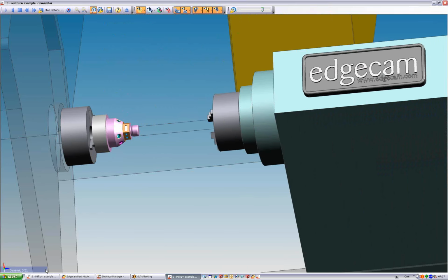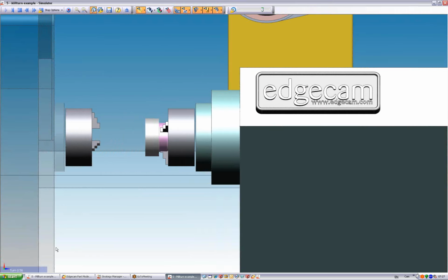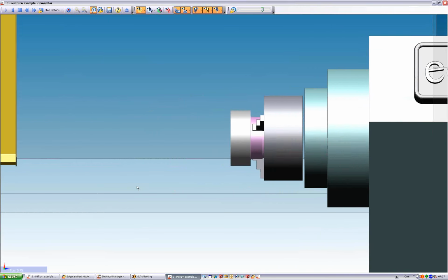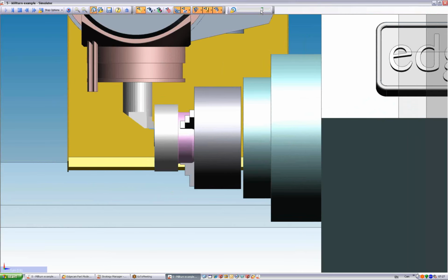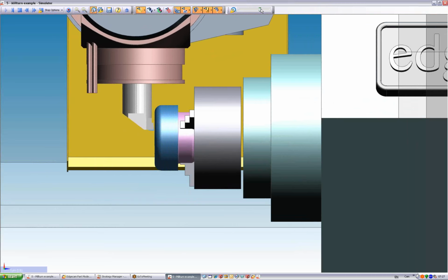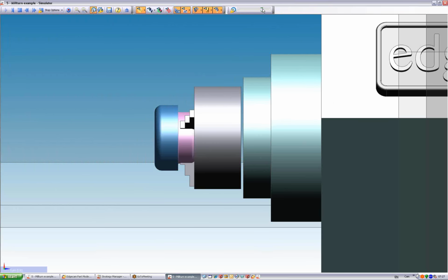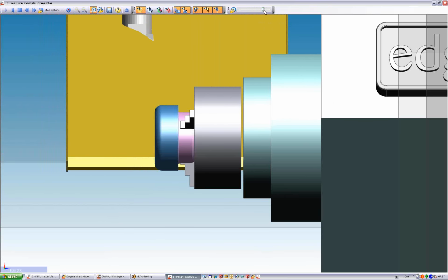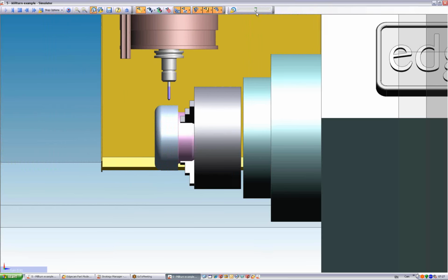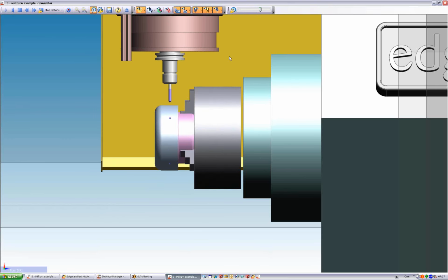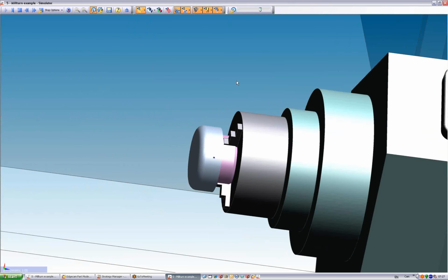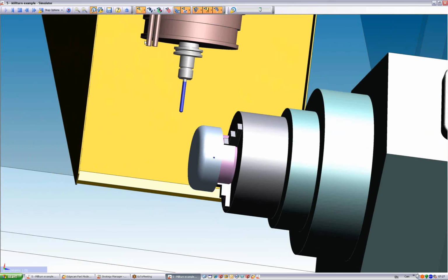Here we see sub-spindle crossing over, and again that's important. We don't want to crash the sub-spindle into a waiting turret. Now we begin machining on that sub-spindle. So we see just straightforward turning down the face, and now we begin to see finished turning, and now B-axis and C-axis begin to work. Okay, so again, Strategy Manager has made all this possible, making the whole process automated.